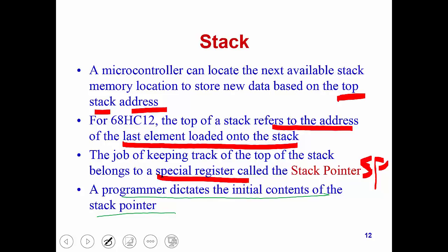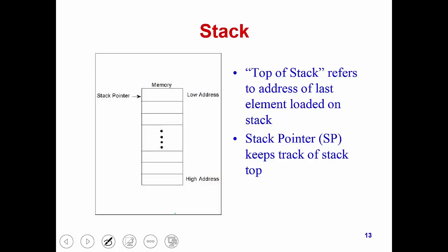So the initial value of the stack pointer, which tells us where the top of stack should be at the beginning, is determined by a programmer. Here I use a memory structure to show you where the stack is, where the top of stack is, and where the stack pointer is.